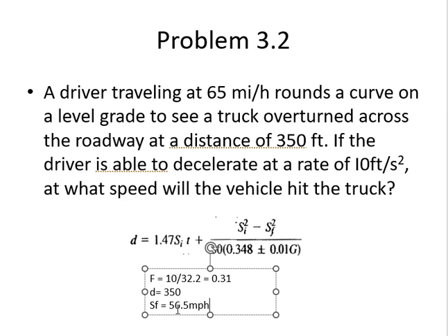This is related to the driver. I cannot control it. I can estimate it. I can have some safety measure there, but I cannot control at what deceleration exactly the driver will decelerate. Our standard value is higher, he is slow. And the second thing which is related to design is that you increase the distance. Which distance? It was 350 feet. Distance between what and what?